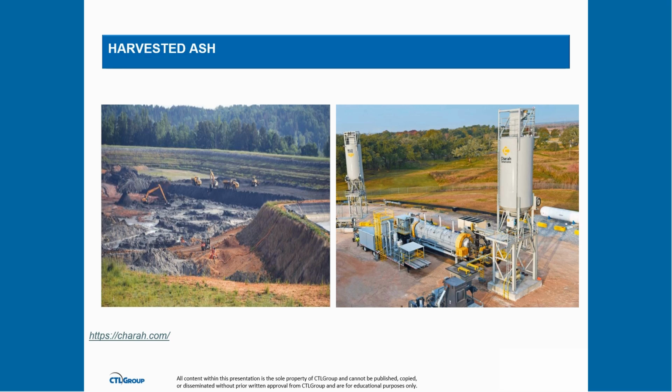And also the reduction in the fly ash reactivity due to agglomeration and partial reaction as a result of long-term exposure to moisture. So these challenges need to be overcome in order for the harvested ash to be used in concrete.